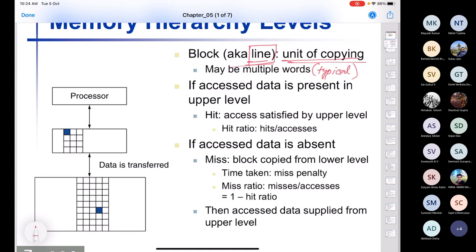There is some additional control circuitry which gets amortized over the entire chip. So the overhead is something like 1.05 transistors per bit of DRAM, and for SRAM something like 6.1 transistors per bit.